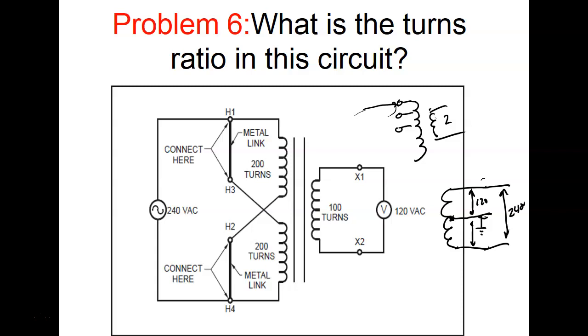That's why we still hook a ground up to 240, even though 240 itself is not referenced to ground, right? We hook the metal up to ground, so that when it tries to induce a voltage into the metal, it can induce that voltage in the ground instead. So if you've got a hot water tank that's shocking you, it's not enough to kill you.